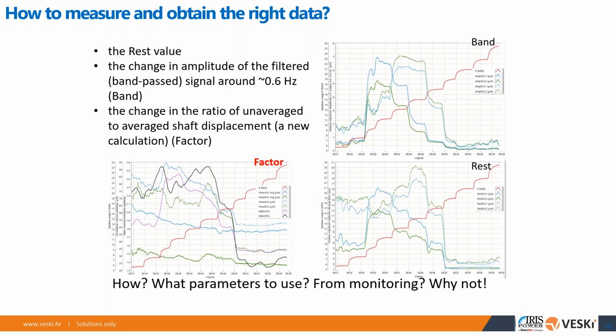But then you take a longer signal duration and do the same calculation, and then you divide the 2 numbers. In normal operation, if this is the power, when you start to increase the power, you can see that this factor is high, and when it comes to normal operation, full load, it becomes very low. So the idea is that I can trigger the alarm on the factor, and this will be a very fast indicator that something is happening, right?